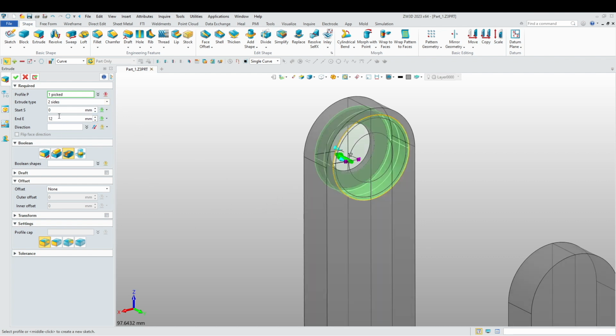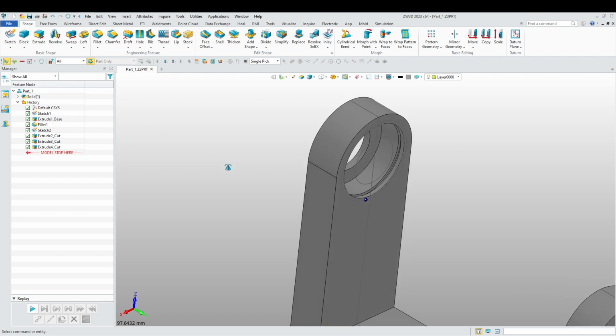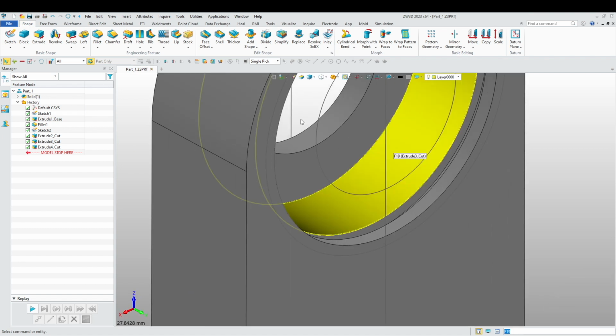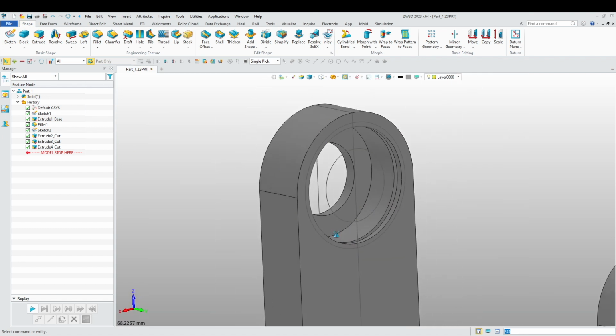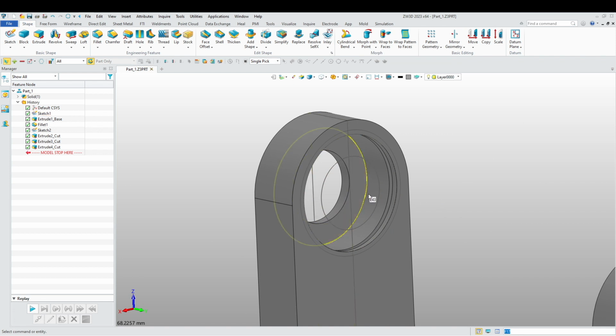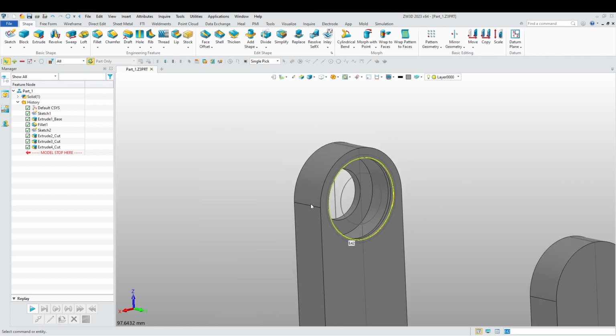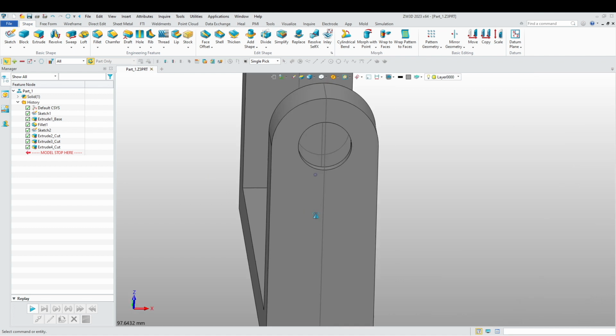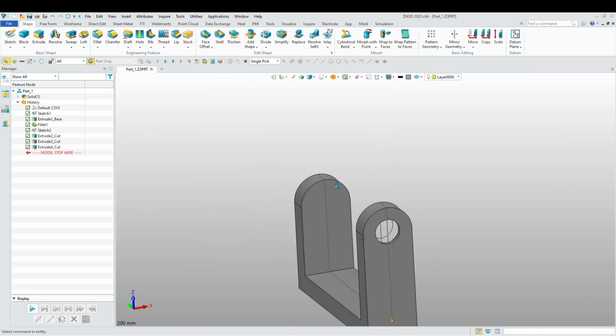It's going to be, now I want to create the casing. 1.7. 1.7 plus 1.3 for the clip and remove. So this is like a little casing, where I will fit a bearing over here and a clip to hold that in place. Now let's create another sketch.